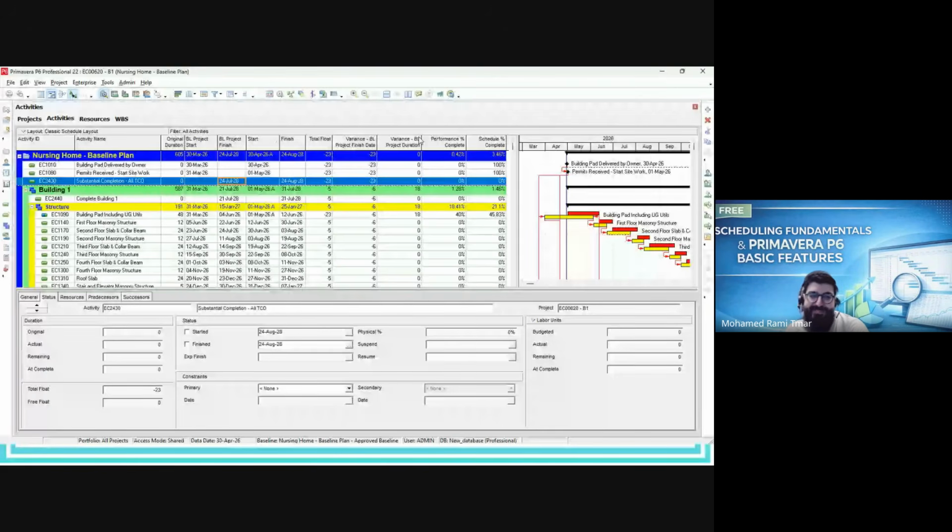Okay, so let me share with you the reality, and then we close the session. You remember the story of multiple paths? All depend on this. You remember the first session when we talked about governance and everything related to governance and the project control govern everything? Because in your project, let's assume you have some activity part of the non-critical path, which is the total float is positive, and that these activity are not impacting your contractual milestone.